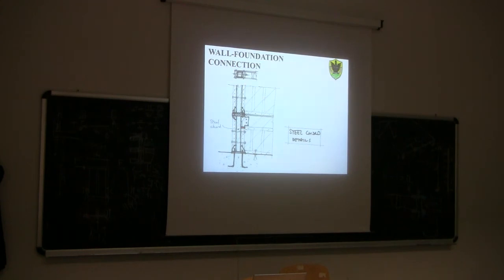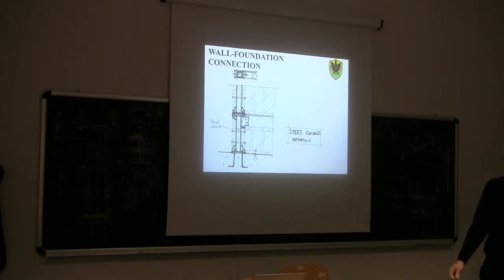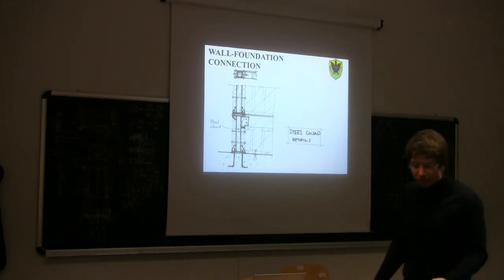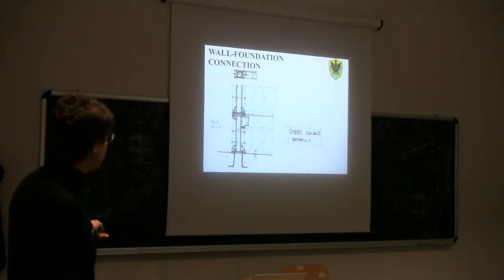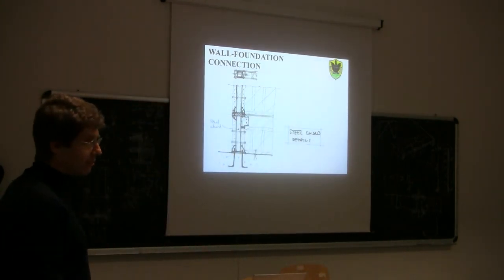So in the end, to transfer the tensile force down to the foundation, we have to use one timber member, one steel pipe, and another timber member, all connected together with this bolt. So that's why I'm saying that to build a 5 or 6-story high building in a high seismicity area using this kind of system, it's a big problem.